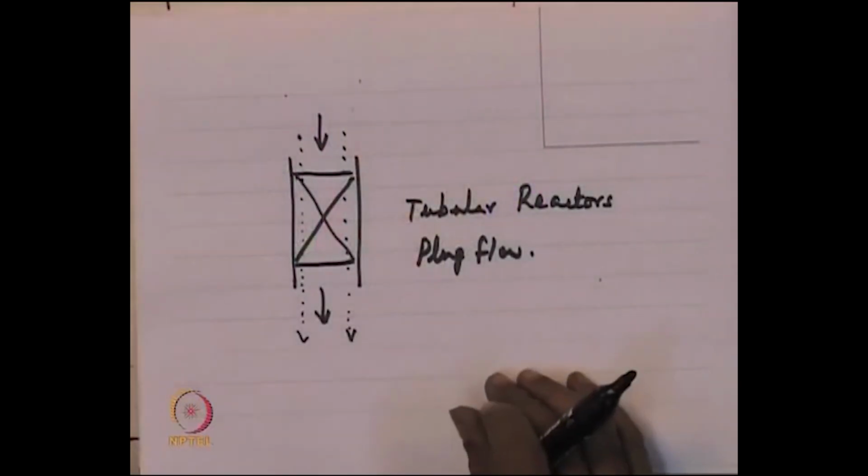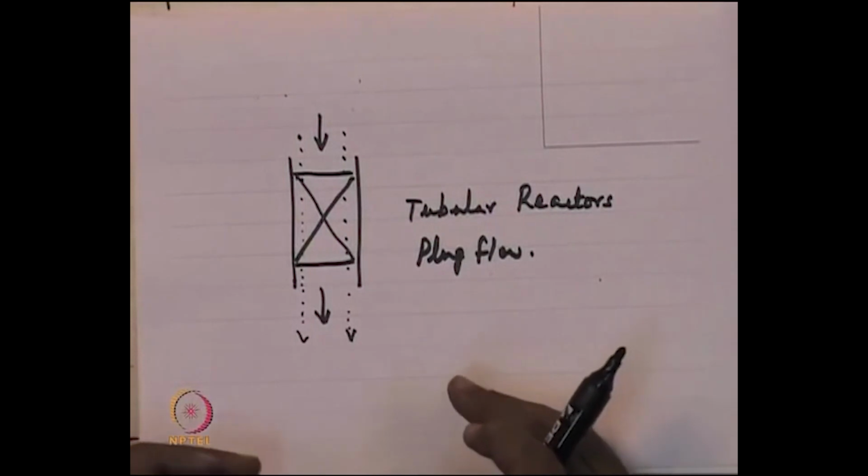Okay. There are several other situations where continuous reaction equipments are quite common, because it permits you to continuously input and output, and at the same time ensure that the temperatures and process conditions are kept uniform. So, CSTR and batch are the stirred equipment that you will see in the process industry, and the tubular reactors or plug flow devices, as we call them, are quite common in the very large scale petroleum and other industries. Okay. So, for both these situations, there are design equations for what we call ideal reactors.